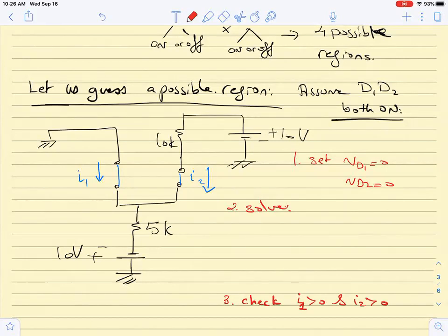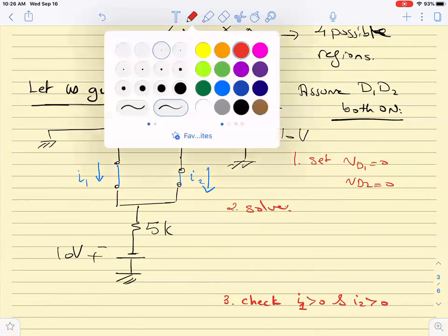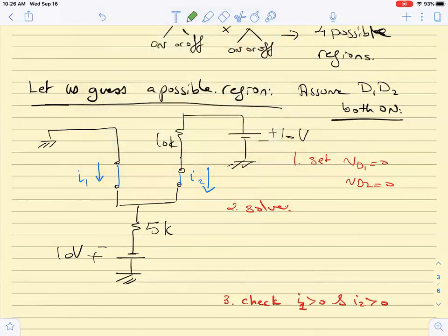Okay? So in order to solve, first thing we notice in this circuit: what do I notice? What is this node? Is this ground or supply? This is ground, right? The green one, which I just labeled. So what is the voltage at this node? 0. So this is 0 here, right? Can I solve for what I2 is?